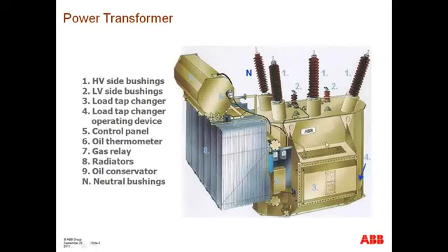Obviously, the temperature inside of the transformer is a function of a couple of things. It's a function of the ambient temperature, the temperature outside the transformer, and it's also a function of the current that's going through the transformer. Okay, the more current, or the more power that's flowing through the transformer, the more RI square losses are associated with that equation, the more energy that's dissipated within the transformer, and that energy is dissipated in the form of thermal energy, which in turn results in a thermal rise inside of the transformer. On that point, you essentially have a balance between the cooling system of the transformer and the power that's flowing through the transformer to keep that thermal rise to a particular level.